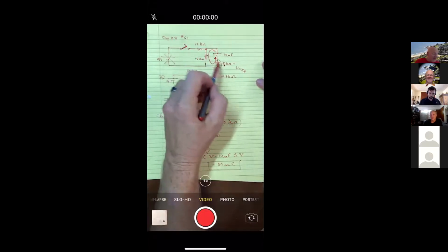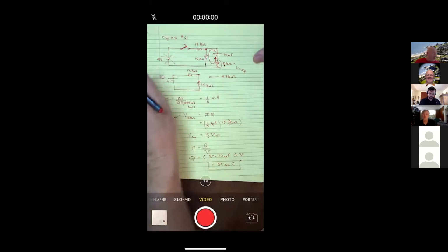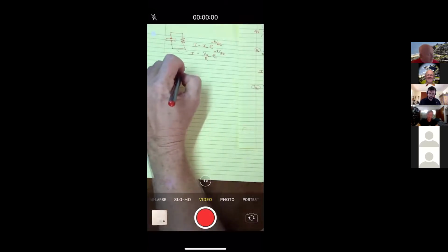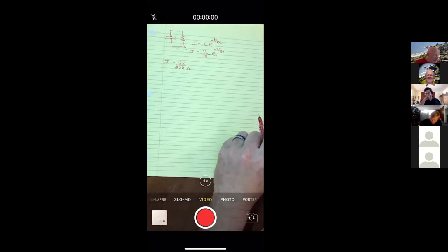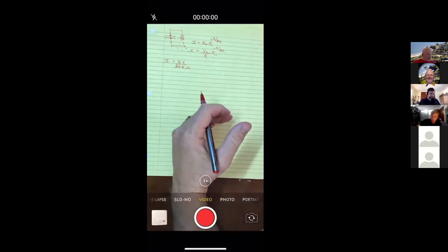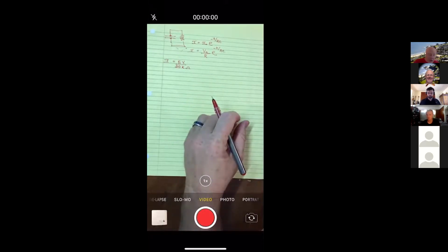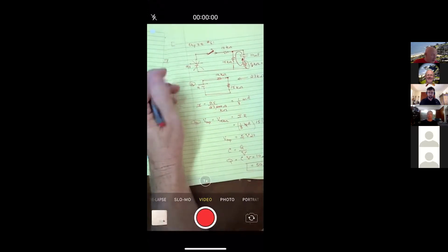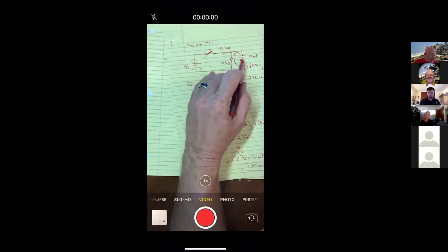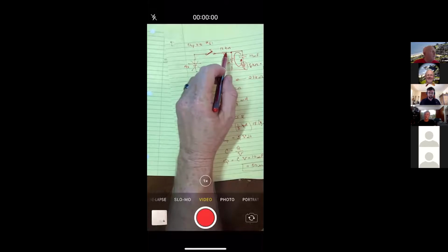So you might think of this as its equivalent, which, if they're in series, you add them. This is 20 kiloohms, so I'm going to put 20 kiloohms here. And so that's probably where the problem might get the hardest, is to recognize that we have an actual discharging capacitor that is only charged to 5 volts, not 9. It's tempting to say 9 because you have this 9-volt battery in the circuit, but it lost some of its voltage before it got to the capacitor across this resistor, which they don't call number 1, but I will.